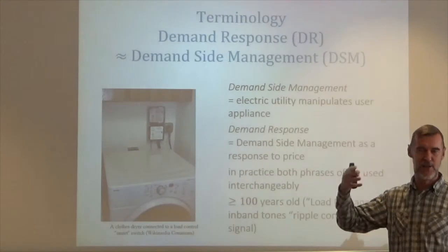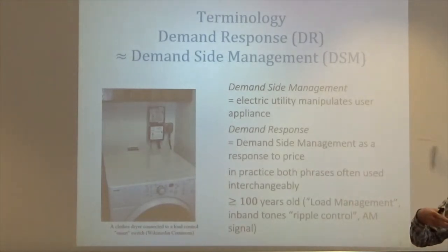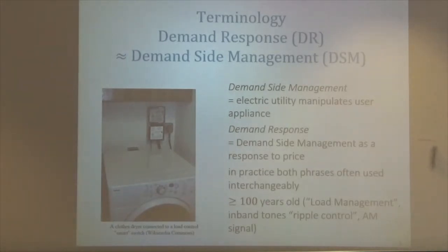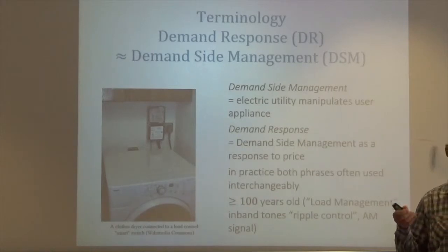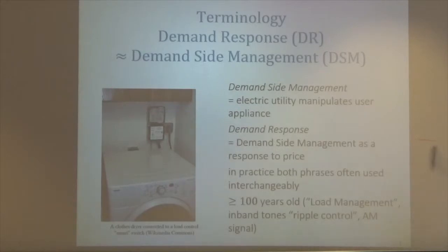Now, some people say they don't. And in Germany, for example, in the past, they used to control the output of nuclear plants, but they were simply dumping. Well, a nuclear plant produces heat, and from heat you produce steam, and the steam engine produces electricity. Now, if you let the steam go in the atmosphere instead of going into the rotors of the generators, you can modulate the power that is produced. But this is cheating. You produce constant power, and then you curtail some of it to produce flexibility.